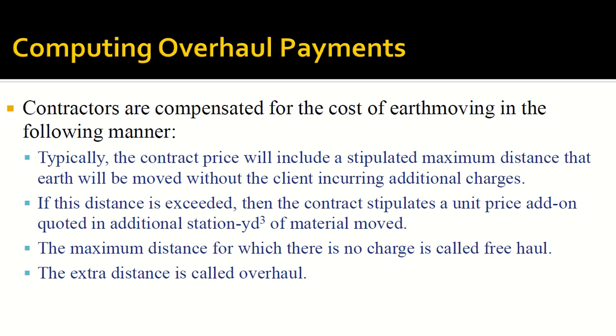Got it? So hauling is transferring the material. You agree with the contractor up to which distance he will transfer the material from cut to fill without any extra payment. Anything more than that will go in overhaul payment. Clear? So it is part of the contract which you have with the contractor. Okay.